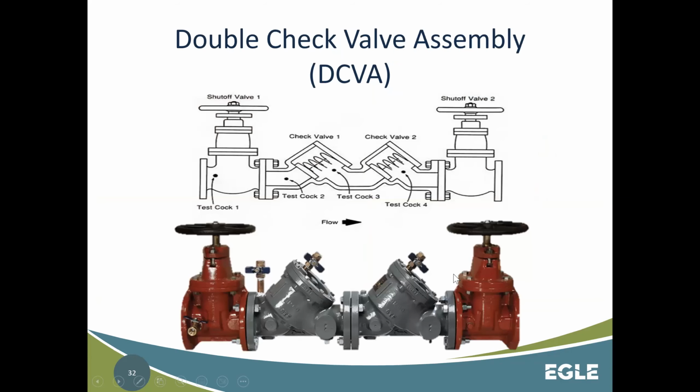This leads me to the next thing, which is the double check valve assembly. This double check valve assembly is a testable assembly. I get that 100%. It's called an assembly, but double check valves are different than RPZs. The biggest reason they are different is that they are for low hazard application or aesthetics. If you haven't caught on to that word yet, you need to know what aesthetics means. Aesthetics means the physical description of a thing, and physical can be color, taste, smell, that kind of stuff, right? That's why I use: does it look bad, smell bad, or taste bad?